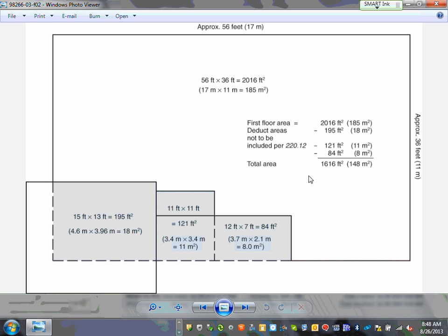A building like Dunwoody, same thing. You take the outside perimeter of Dunwoody. You don't multiply by 3 because it's not a house. You multiply by 3.5. That's it. We're going to be using this table for commercial, industrial, everything else.